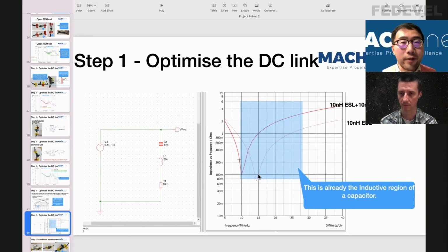So I think that's a very good point for anyone to take: you spend lots of time looking at the data sheet of a capacitor, but then you put it in a circuit, and the circuit actually introduces more inductance than you thought. So you think you picked a capacitor for, I don't know, 15 megahertz, but once you connect it to your circuit, because of the leads to the circuit, it actually may not work for 15 megahertz, but for something lower. And at 15 megahertz, it can be even worse, because instead of placing a capacitor, you place an inductor. Exactly. Yeah, that's the point we'll try to make.